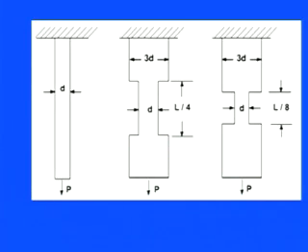In the same diagram, we have all three bars. One has a uniform cross section with load P applied and diameter d. The second has the same length, with no change in length, and the applied load is P, but there is a dip in between. The first and last diameters are 3d, but in between 1/4 of the length has diameter d only.